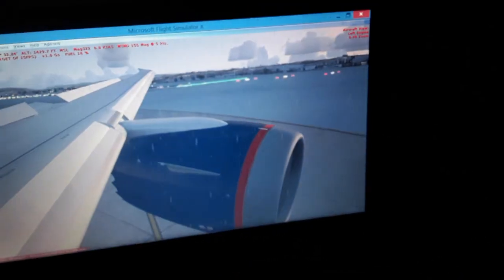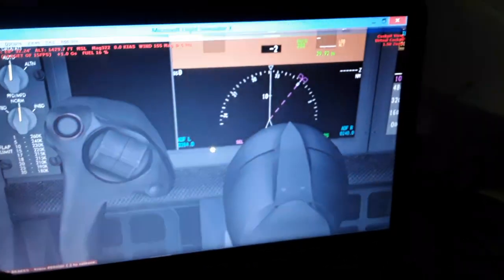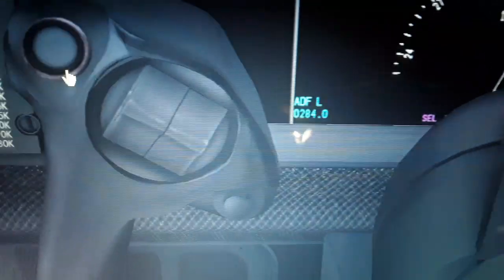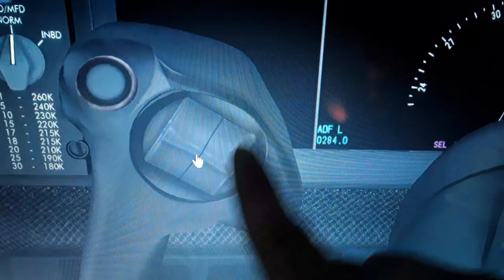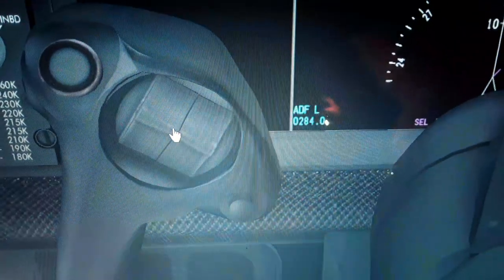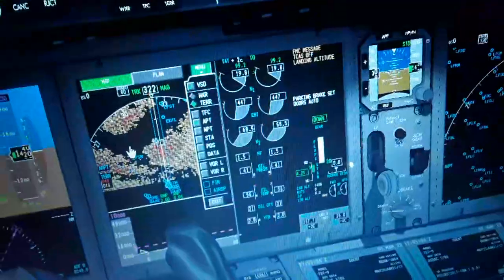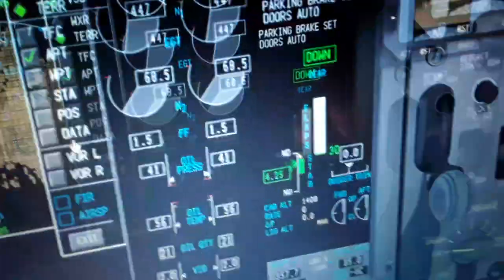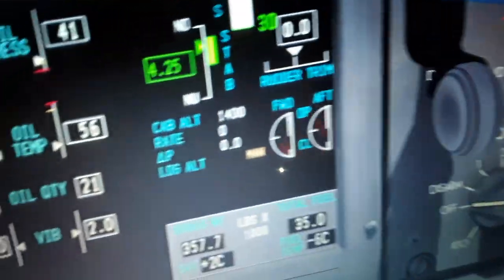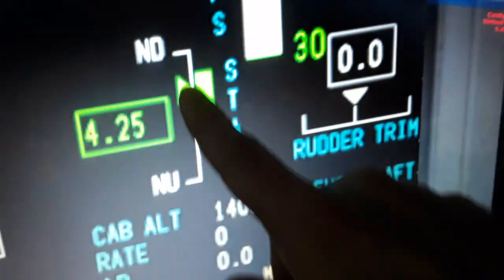Also you have the trim of the elevator surface as you fly. So you can trim like this. You use the elevator trim, which pitches the nose of the aircraft up as you fly, and this way you pitch the nose of the aircraft down. You trim the elevator down. So you can see the elevator position in degrees over here in the display, how many degrees you have. So you can see nose down and nose up over here.